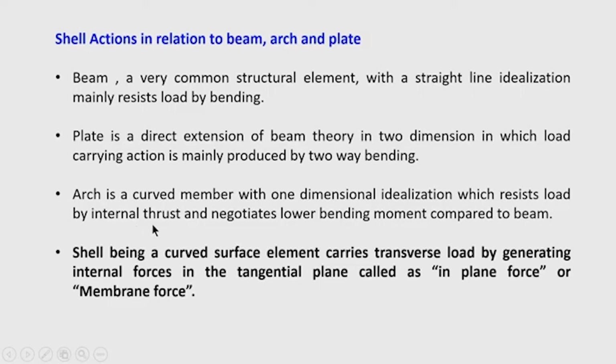Because of the curvature of the member in the plane, internal thrusts are generated, because when an arch is loaded vertically downwards, say live load and dead load, whatever may be, the arch will try to spread, but this is prevented by generating a reaction component at the support.